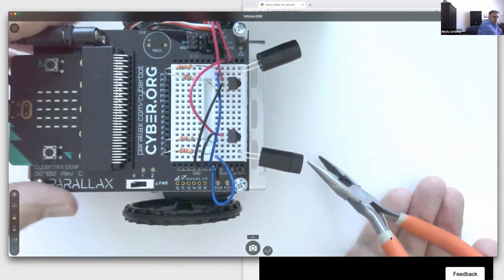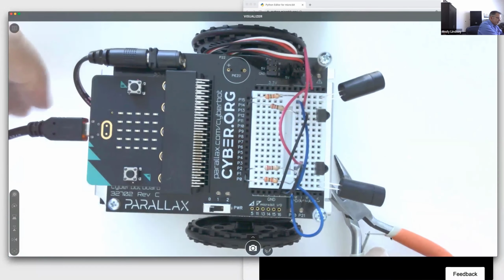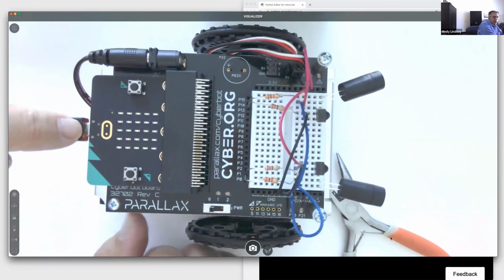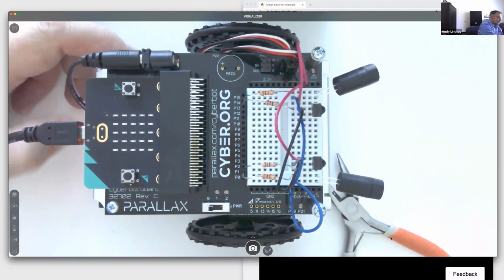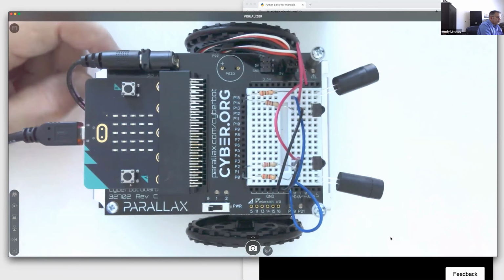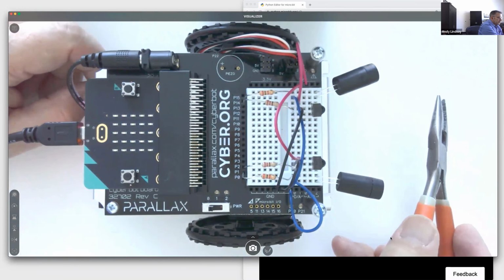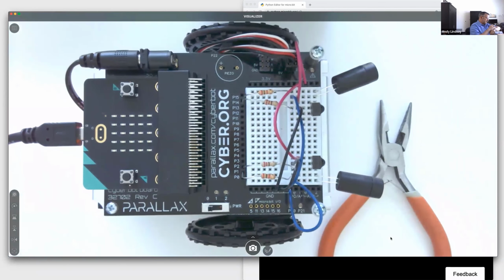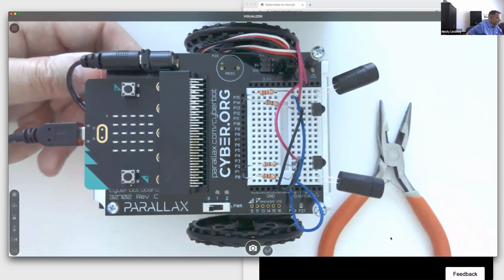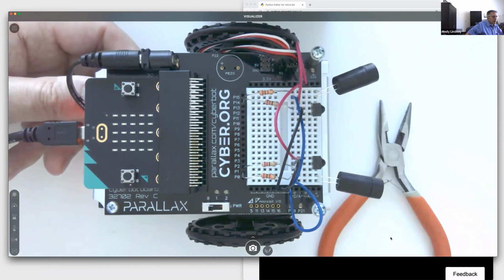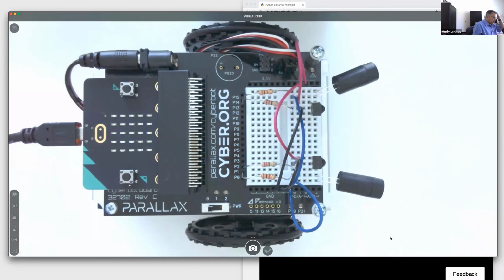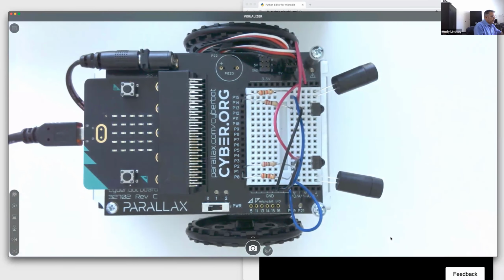So yeah, I would say unplug the battery, unplug the microbit, and that's a good practice anyhow. That's true. Yeah, and then you're okay. Ideally, if you want to really go for the electronics training, have an anti-static mat and an anti-static bracelet. Those are fair game. It's not a kind of equipment that we sell, but electronics outlets like DigiKey and Mouser are going to carry those. And you basically plug the mat into the wall and it gives you a ground connection.